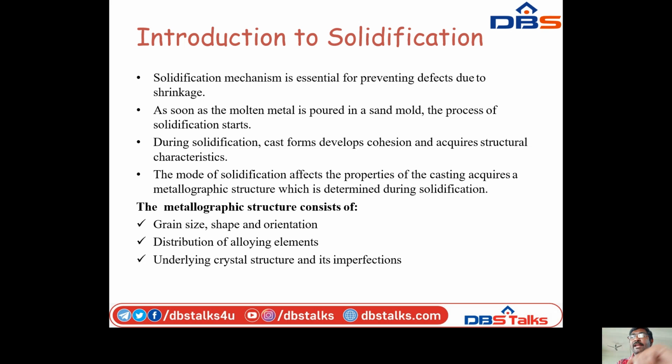Solidification of casting may take place at constant temperature, over a range of temperature, or both, depending upon the composition of the metal. During this process of cooling, the solid metal cools to room temperature. Understanding the solidification mechanism is essential for preventing defects due to shrinkage.